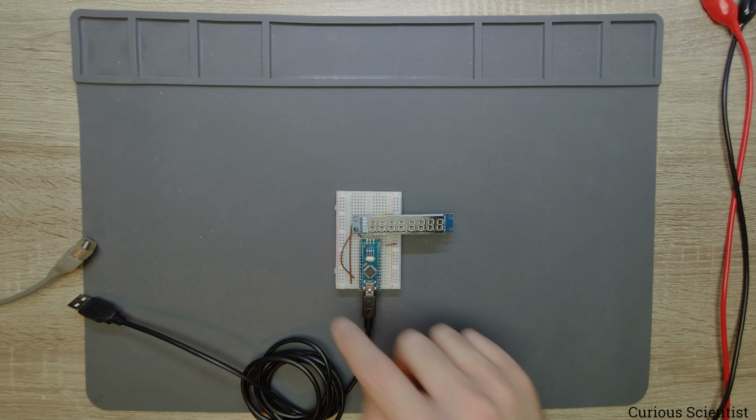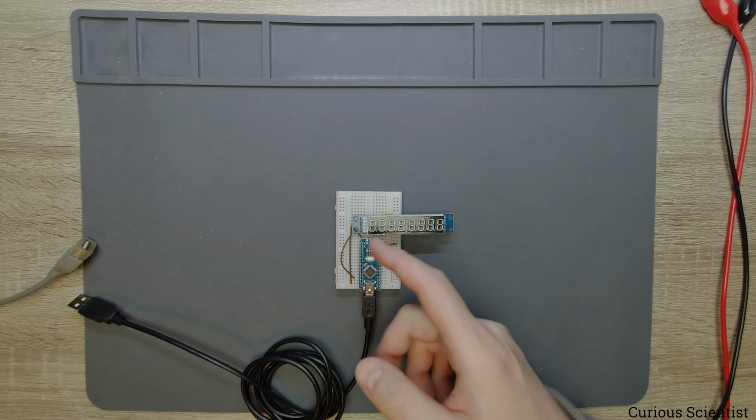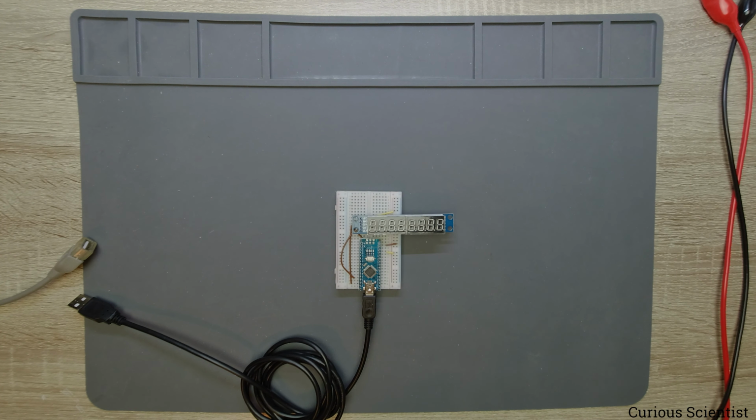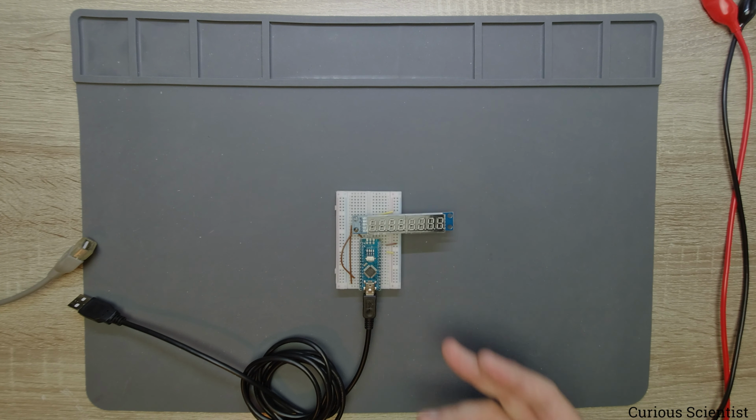We have 3 SPI pins: DIN, chip select, and clock. Those are the normal SPI pins, 12, 13, and 10. You will see it in the code. It's fed by +5 volts, and of course, the ground is also connected to the board. So it's a very simple connection.